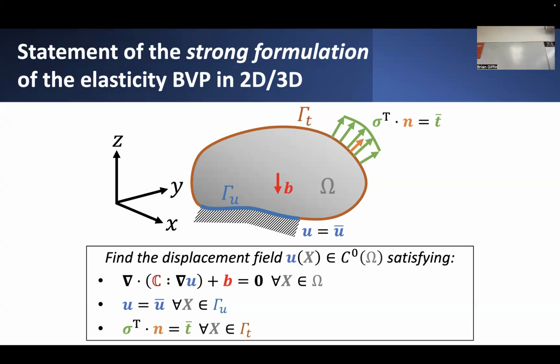We've imposed some requirements on the displacement field itself having to be a continuous function. But let me ask you, what if this object didn't consist of some uniform material? Maybe it was actually two materials glued together along some shared intermediate interface, such that if I were to define some of these material properties as characterized through this fourth rank constitutive tensor, maybe I could define these properties such that they jump in value as you pass along that discrete boundary.